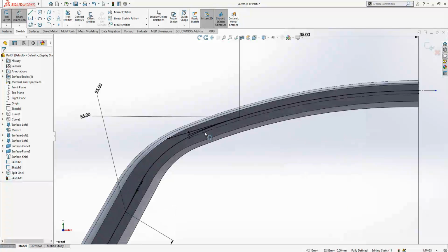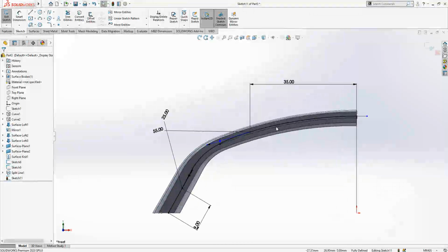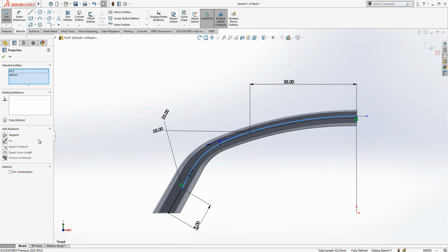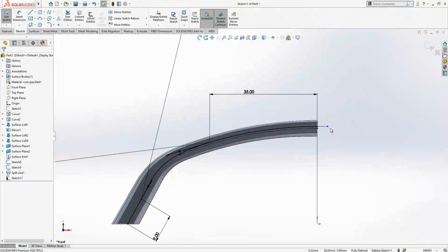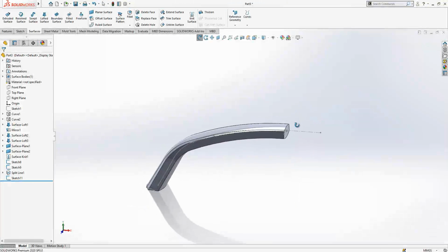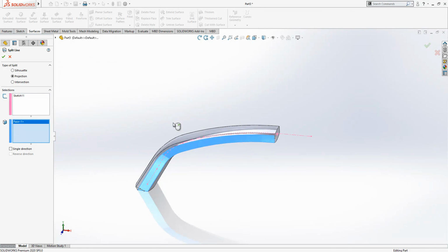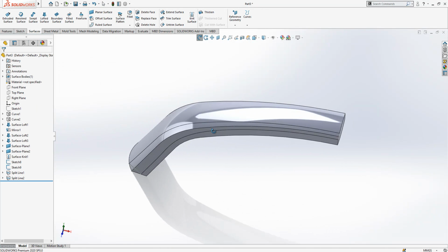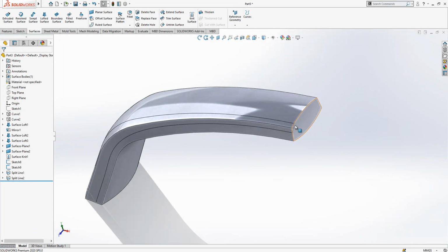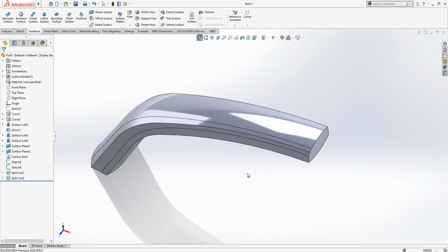Okay, quite nice. We need to make here a trim operation. The unnecessary part should be removed. And here to here we have again a tangency. Everything fully constrained. This is an extension of line. It's not very problematic. We close it. So split line and split on this edge. What I did now, I'm going to make a variable chamfer and I create boundaries of my chamfering. I could make it differently, but this is much more consistent. The real work will be done in this way.